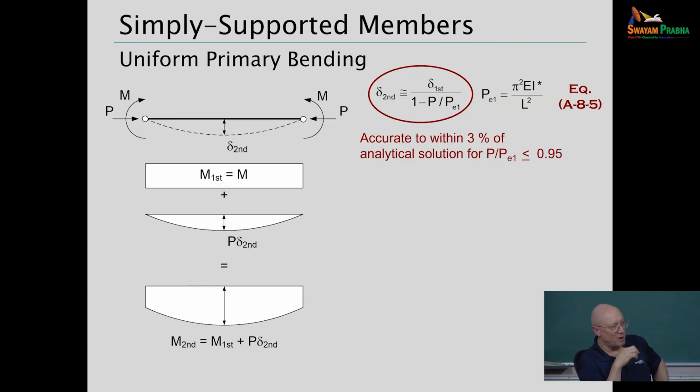But the subscript 1 is a notation that the AISC standard uses to basically refer to a braced buckling load or a non-sway buckling load. If you see the subscript 1, that's non-sway. There's also an amplifier that we're going to talk about that's B1, that's for non-sway.